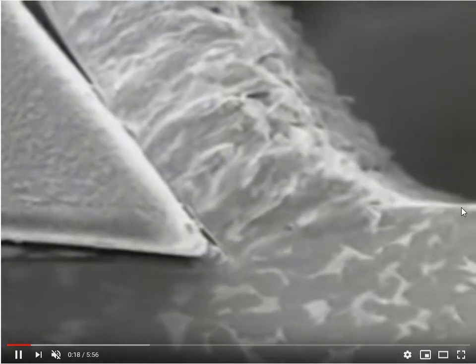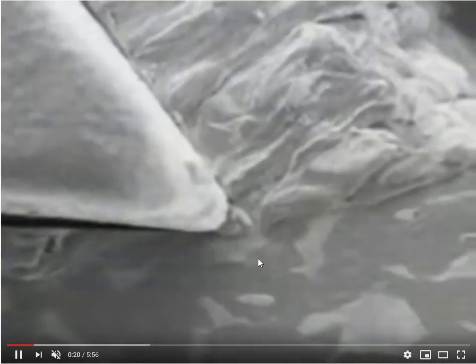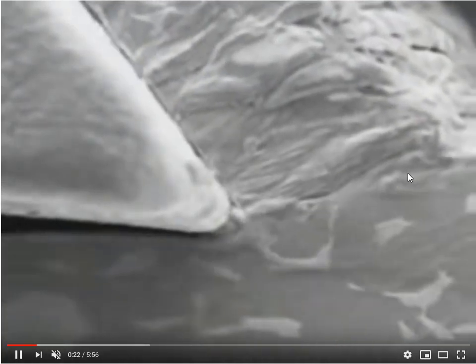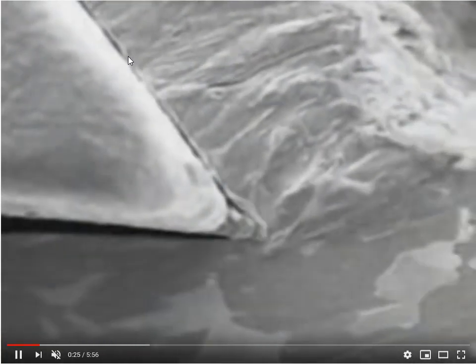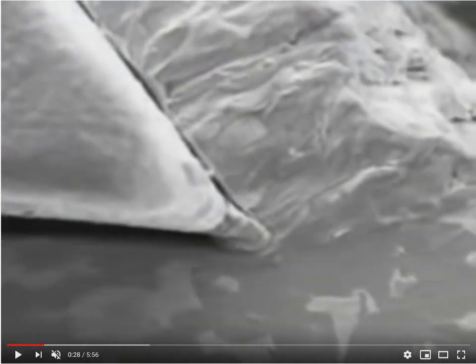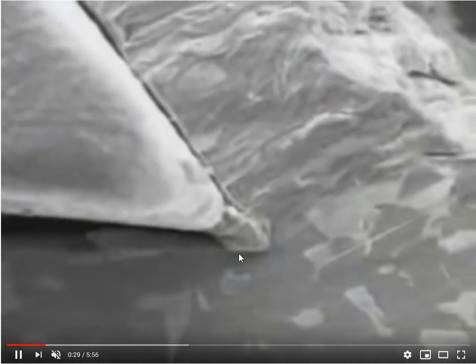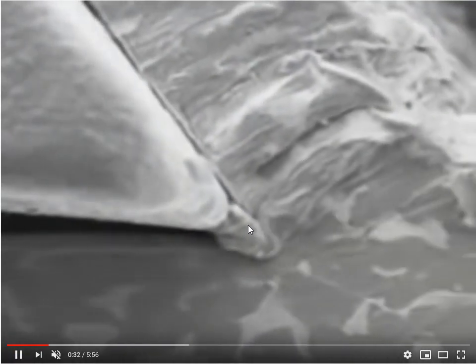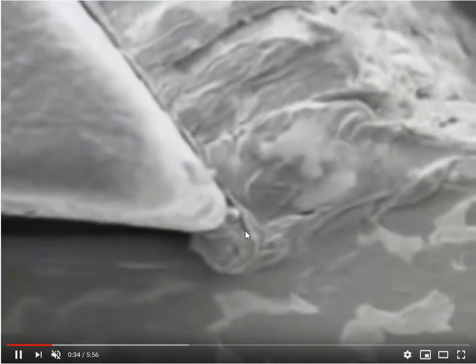So here's the surface of the material, and the material is actually plowing up the front of the tool. Okay. And if you look at the front of the tool, you'll see what's actually the nose of the tool. Okay, and here we have the relief face of the tool because we don't want to rub. And what you're seeing appearing there is what is called built-up edge. And that built-up edge you'll see will form, and then it will break away and go past.